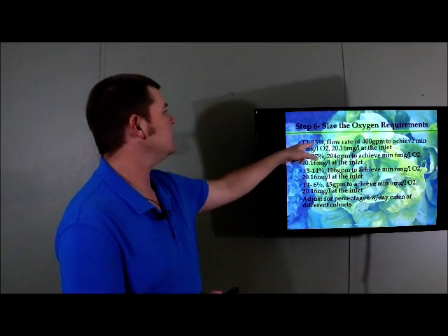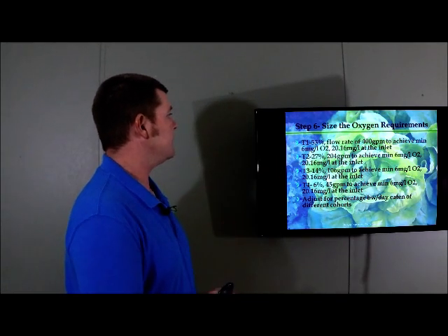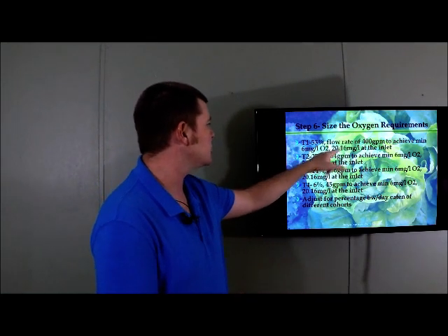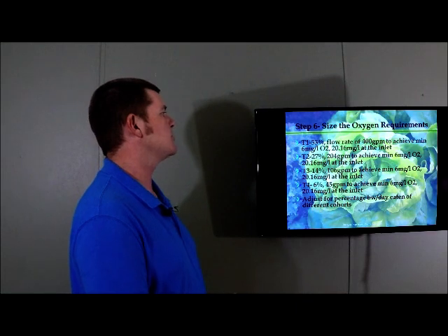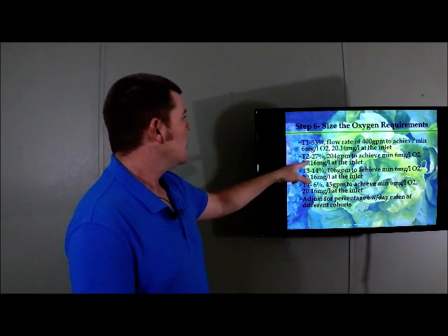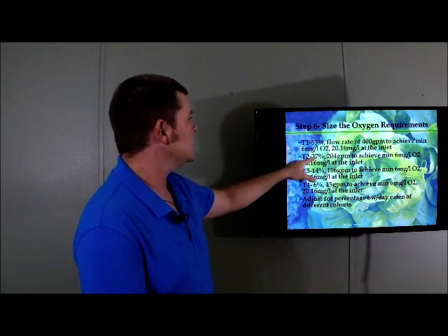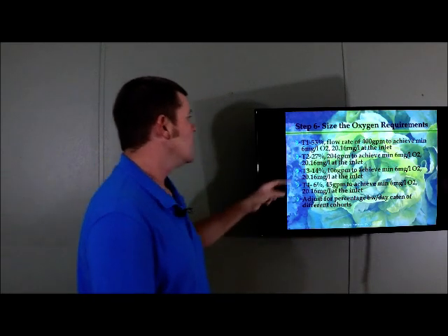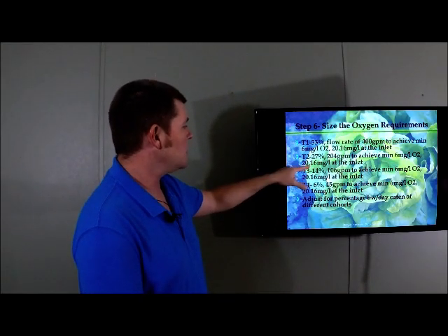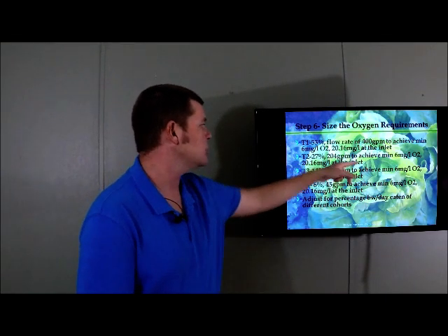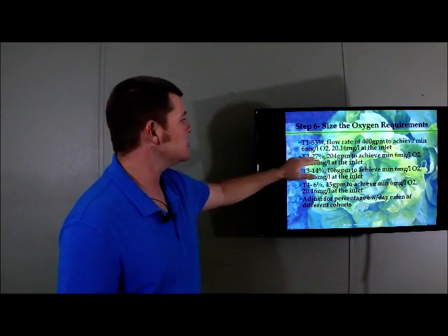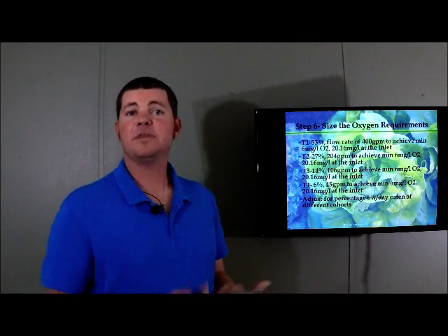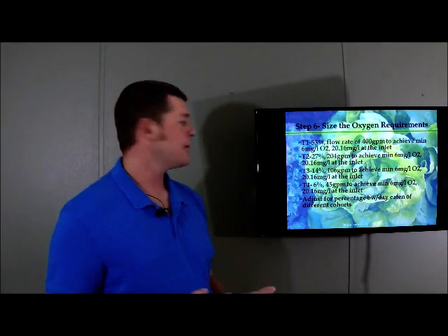All right, so tank 1, 53% of the fish mass. We have a flow rate of 400 gallons a minute to achieve 6 milligrams per liter oxygen when we inject at 20.16 milligrams per liter at the inlet. Well, tank 2 is 27%, which drops the flow rate needed to 204 gallons per minute to achieve 6 milligrams per liter at 20.16 milligrams per liter injected at the inlet. So because we have less fish mass, we don't have to inject the water as quickly with the same amount of oxygen in the water, okay?